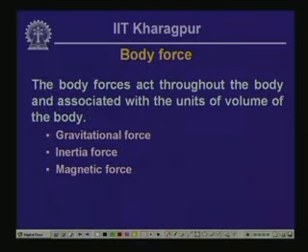Well, having known the units, let us look into some aspects of the forces that a body, or I mean a member, is subjected to. Now, we come across a term which we call a body force. Body force is basically associated with the volume of the body, and thereby it is a distributed system, a force distributed over the entire volume of the body. In that sense, the gravitational force, the inertial force or the magnetic force are the forces which we term as body forces.